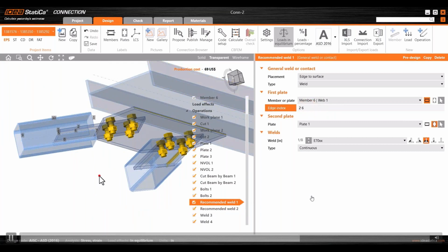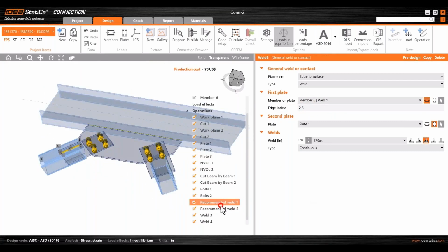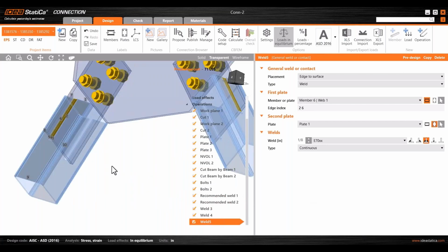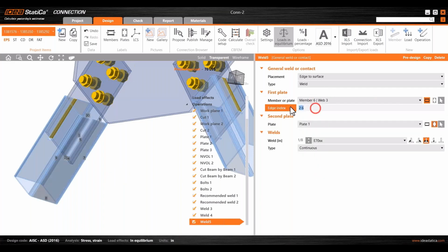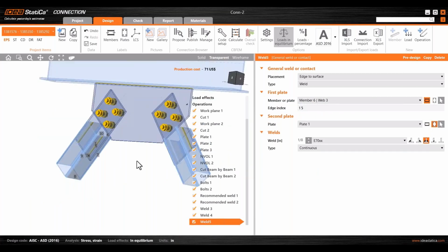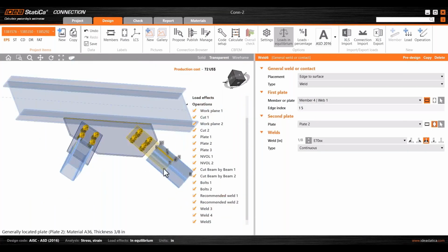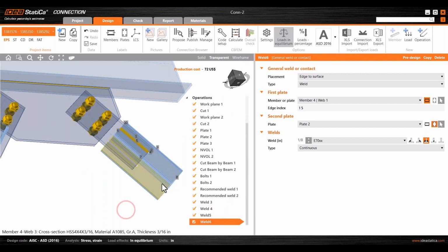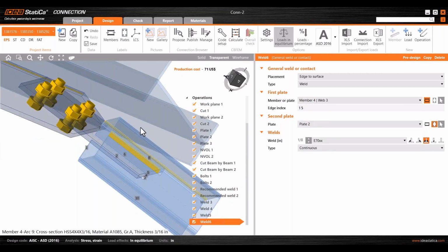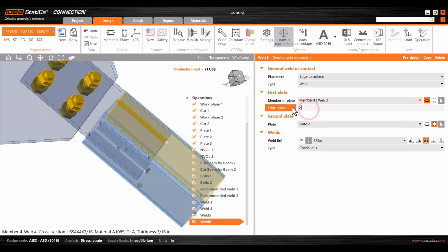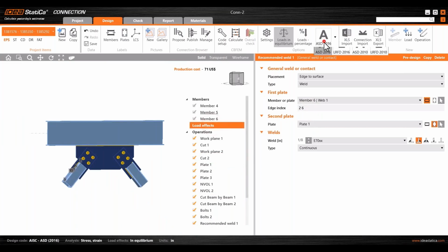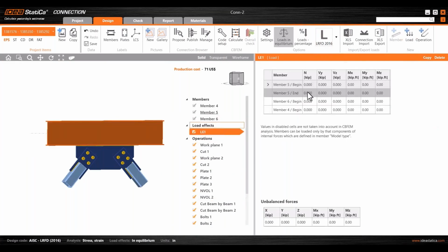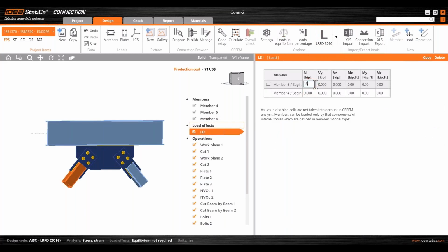Another thing to remember is that you need to change the model type, because that model type is something from IDEA. It is not from other software. So here, for instance, for the bracing elements, I am selecting the model type BYBC, sorry. So that is the model type for these elements. And finally, add loads, because loads are not transferred from Tekla Structures. So make sure you have everything correctly modeled here.